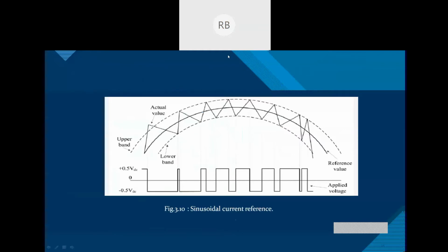In this hysteresis control method, it has a constant on time and off time. This is the advantage of the hysteresis control method. It takes only one current command, that is, it is used to limit either the maximum input current or the minimum input current. The hysteresis comparators are used to impose the hysteresis band around the reference current. One of the most important advantages is its simplicity, and it acts very quickly.